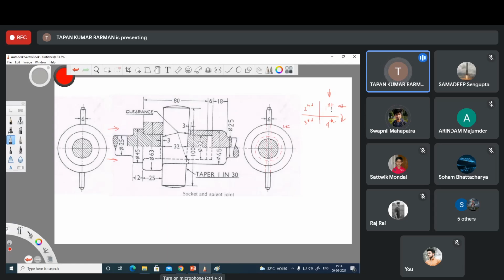One point may be here, another point may be here, and you have one line in descriptive geometry. Another point may be here, also here, and for this line you can find the true length, all other positions of this, or intersection with another line. So in descriptive geometry you can do it, but when you are discussing this type of component drawing, then it is not possible to use second and fourth. So we avoid second and fourth, we use first and third.